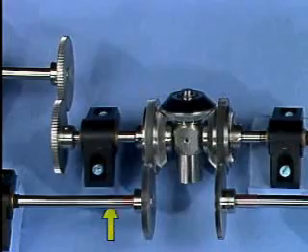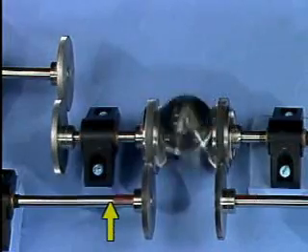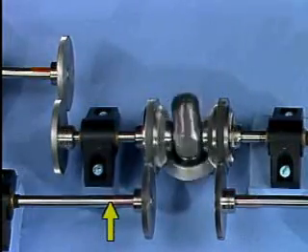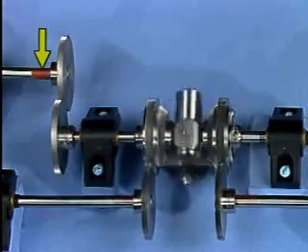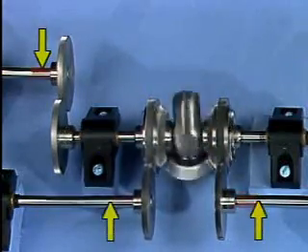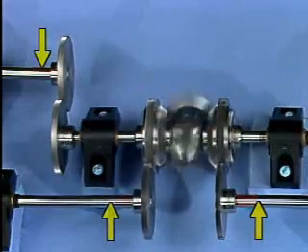If we slow down this shaft, the differential now sees a difference in the input speeds, and the output shaft rotates. The output speed is proportional to the difference between the input speeds. Mechanical differentials are used in a variety of applications. We saw how they were used in cars. They're also used in many measuring instruments to mechanically monitor and compare rotation of equipment components.